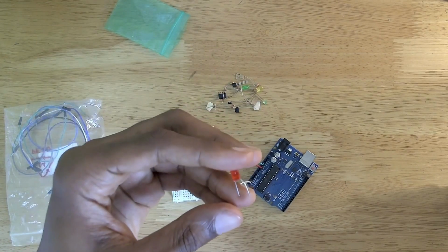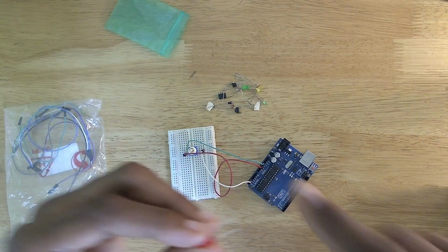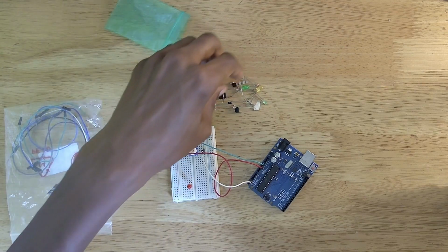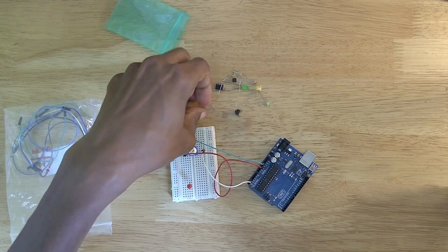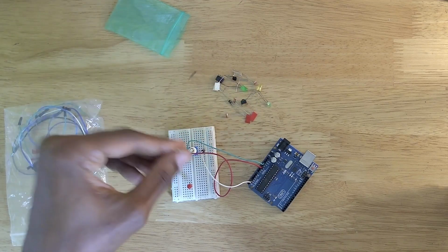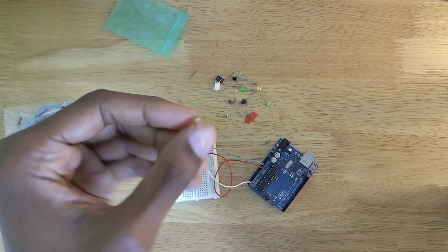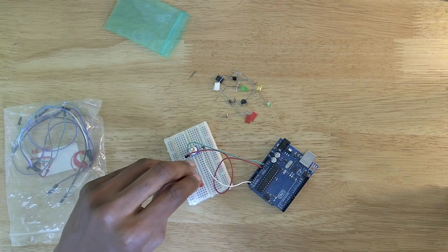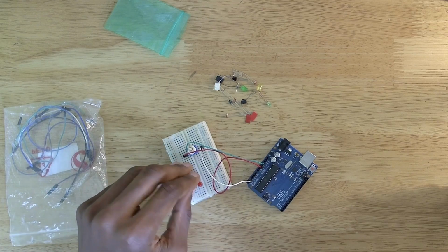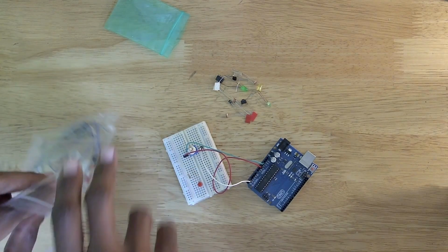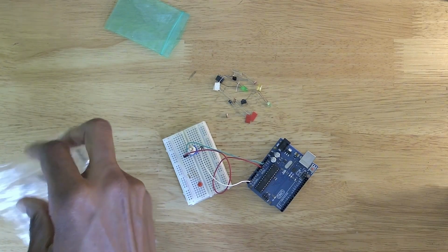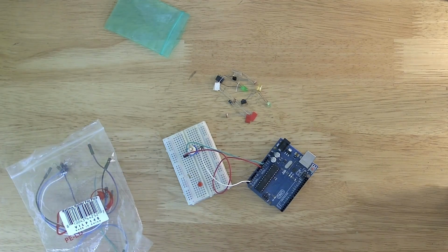Alright guys, now we're going to need to connect an LED. There we go. So this is the longer pin, so it's the plus. Go and put it like this, and I already have a resistor here. So there is a resistor, you can see here, and then just plug it like this. There you go. Let me get some cables to wire all of that. So this one I put on pin 11.